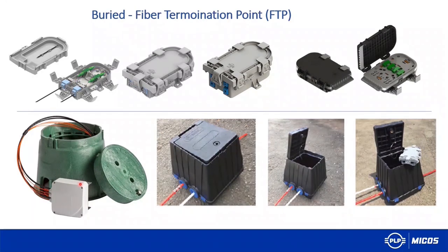Yes, here you can see how it looks like. Of course, this one is not buried, but this can be a mini manhole, or let's say a Toby box, where it doesn't have any load, so you cannot go with the car through it, so you cannot put it on a road or inside the parking lot. You can always put it in a green area or in the garden, and this is how the closure is connected. So yes, this buried fiber termination point is very popular, and for example, is used in the UK, where they have it under the ground in pavements.